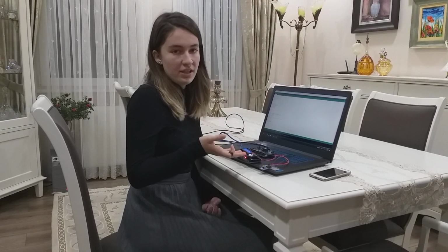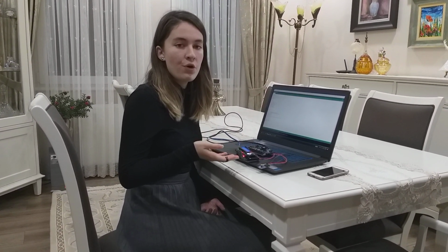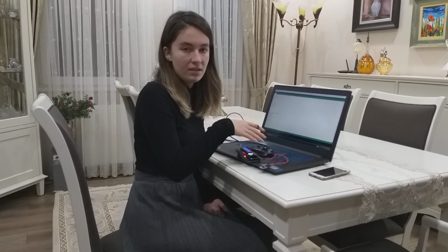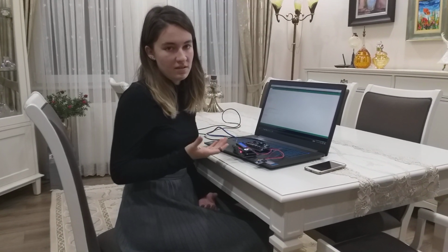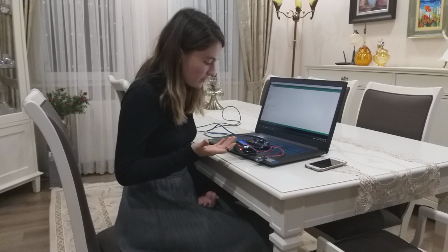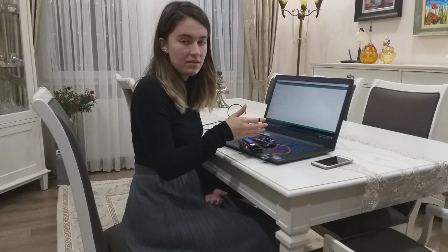In these 16 bits, the first 4 bits were 0 bits, and they were sent at the beginning. The later 12 bits were the actual data bits, and I received these data signals at the falling edge of the clock signal, exactly at the 16 clock cycles.